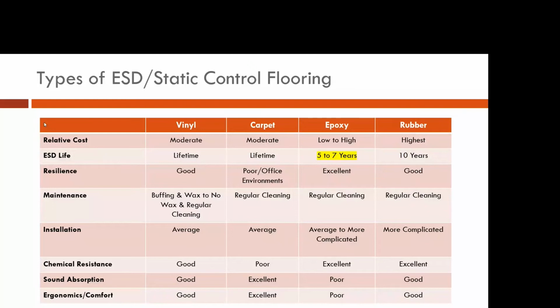Your various considerations for your installations. A lot of that depends on what the existing subfloor is. Is it going to need shot blasting, moisture barriers? Have you done moisture testing? Is the floor built in the 1950s and asbestos could have been used in the glue that adheres the tiles down currently? Now you're talking about remediation, which is extremely costly.